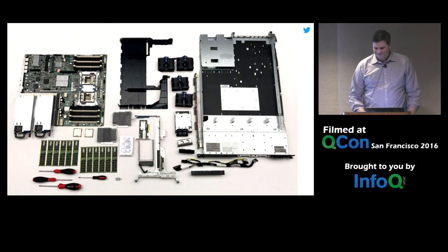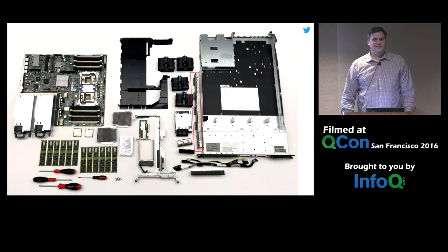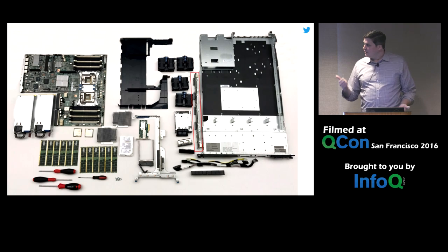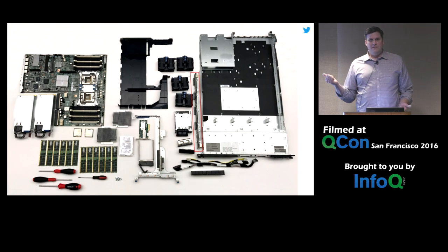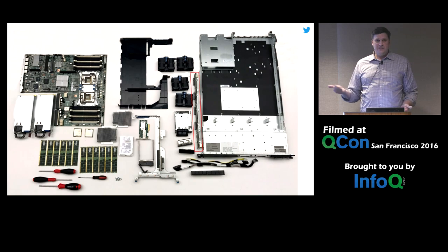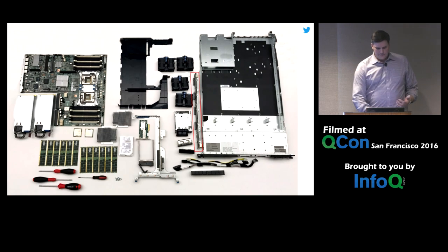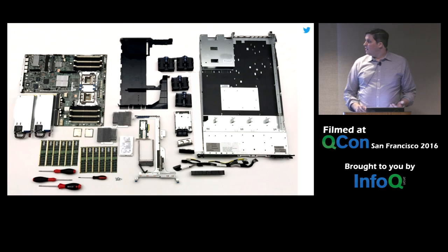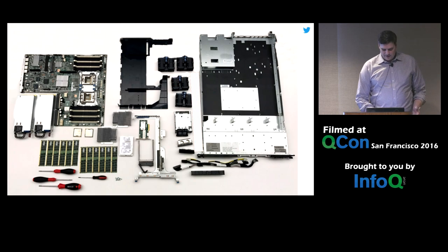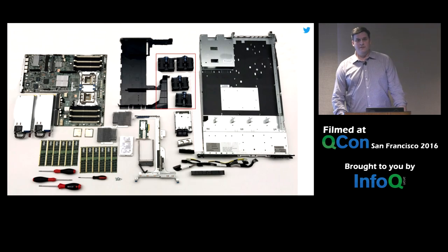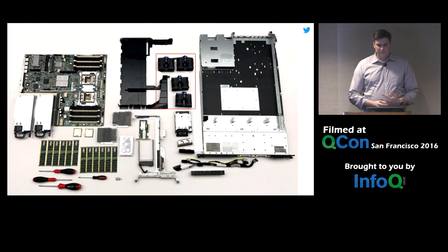This is my favorite. There's a SATA mid-plane for hot plug. I didn't even realize how much I hated these things until I wrote this presentation. This thing obstructs airflow. This one was passive, so we really didn't have a failure problem with it, but we're going to get rid of it. Then the next thing that happened, because that SATA mid-plane was in there, there are 16 fans to try to move air through this chassis.